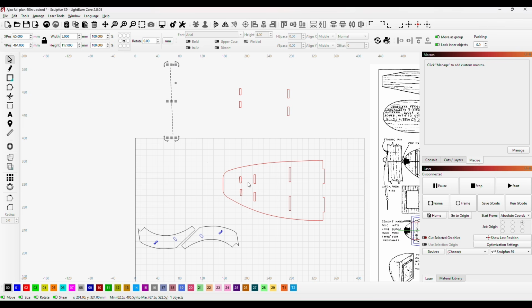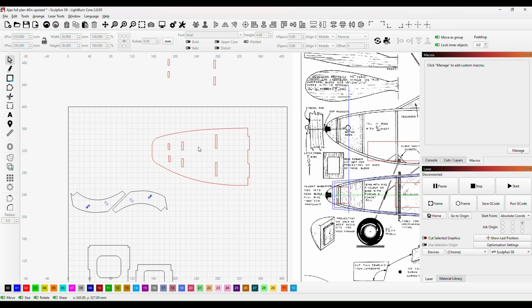We also need to offset our motor to the right slightly, and the reason for this is the torque effect will tend to make the aeroplane tilt to the left, which will cause it to fly to the left.